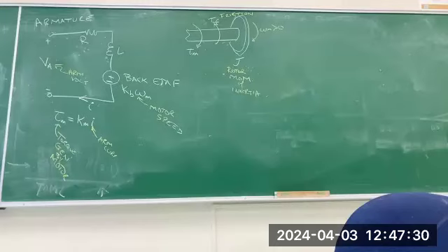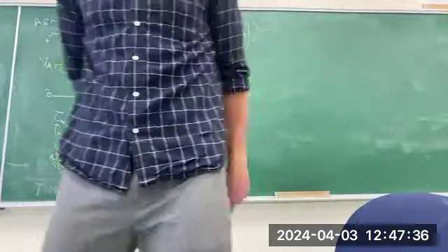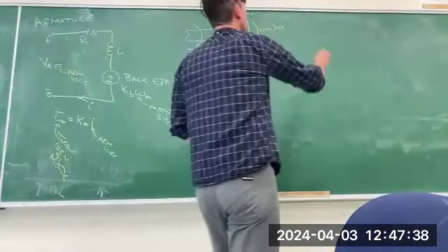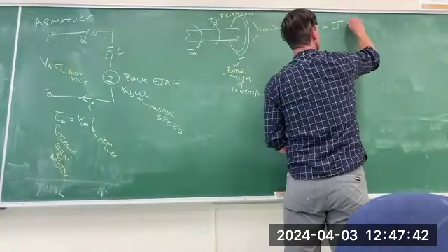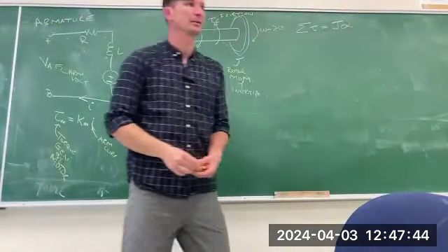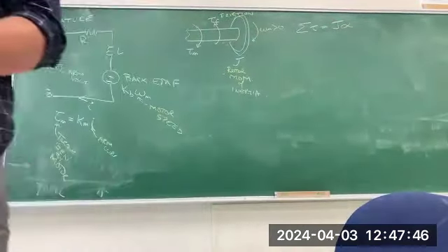I would like you to take this free body diagram and write out Newton's second law, given that notation. Good, you've all memorized F equals ma, but have you heard of its cousin, torque equals J alpha? Sum of the torque is moment of inertia times angular acceleration. This is Newton's second law in our rotational frame.